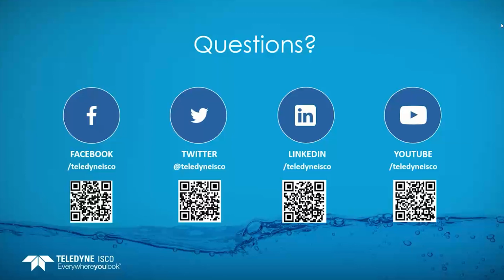Thanks, Andrew. I want to add one thing to that. The other option, if you don't have the two sensors to read the two different locations for the calculation, is to use an area velocity sensor. We've had some clients with common submergence of their flumes, and what they've done is take our wetted area velocity sensor and put it in the upstream pipe, because it will then read the level and the velocity to calculate the flow. So that's just another option for you. Sharon, do you have more questions?